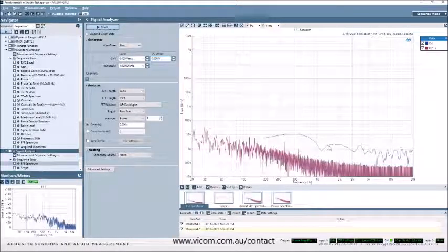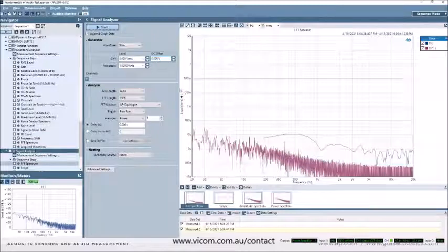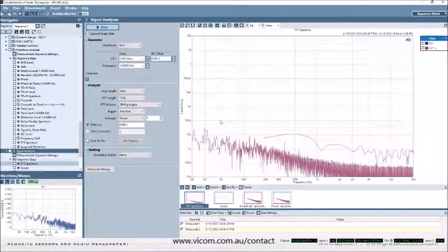So here I did a really short FFT, and below it I did a much longer FFT, and you might say, well, did the noise go down? So this is an RMS scaled FFT, and the key is this: if I am measuring a coherent signal like a sine wave, they will both return the same amplitude. But if I'm measuring noise, the longer the RMS scaled FFT, the lower the amplitude of the noise will appear to be.